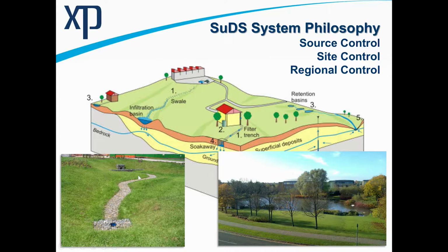This is an infiltration basin in the Midlands, constructed quite a few years ago. You have a trench taking the low flows, and then when the extreme rainfall events occur, like the 30-year, Dave's designed this infiltration basin to fill up to a certain level, to provide you with flood mitigation measures to ensure there's no flooding for the 30-year return period. We can gain benefits here.